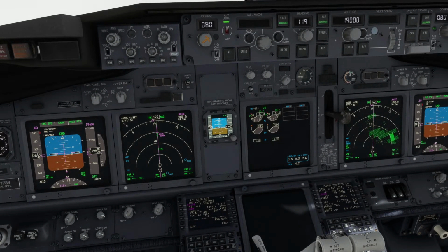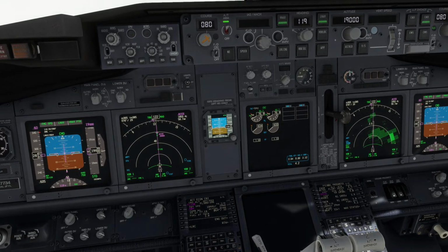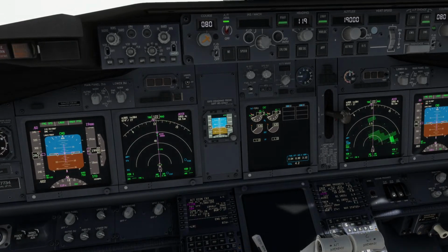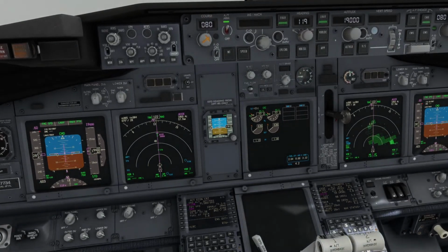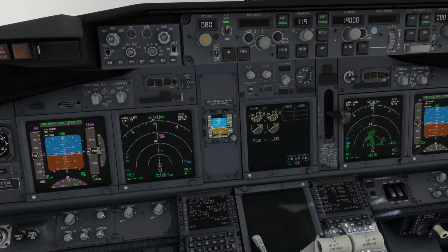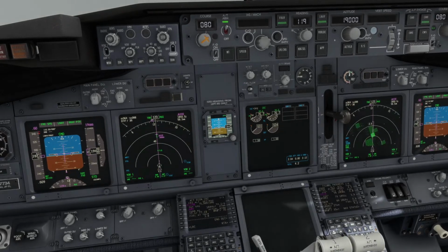JP says method is given in lesson plan. Yeah, it is there. I just found it again. Thank you so much. So with these conditions that we have right now for the weather, 3,000 feet overcast, and our minimums, they are at 700, it's not a big deal. We may have some rain, but it says light rain, so I would continue towards destination.